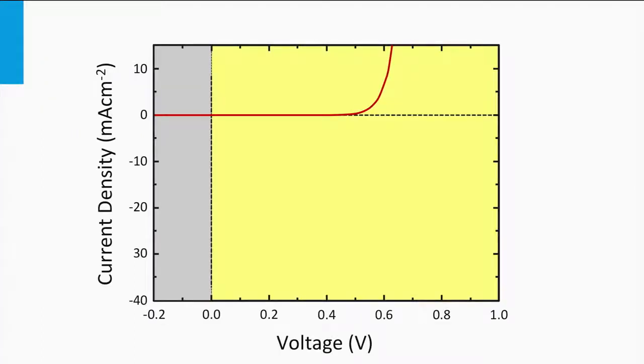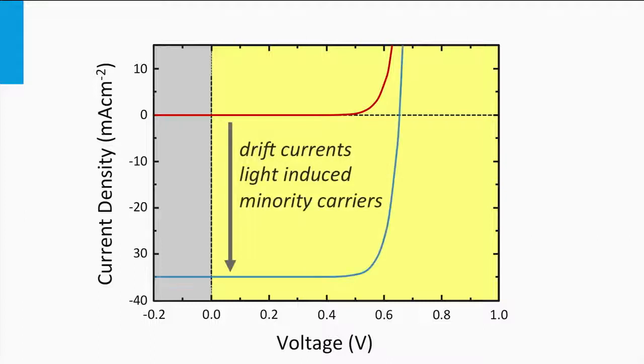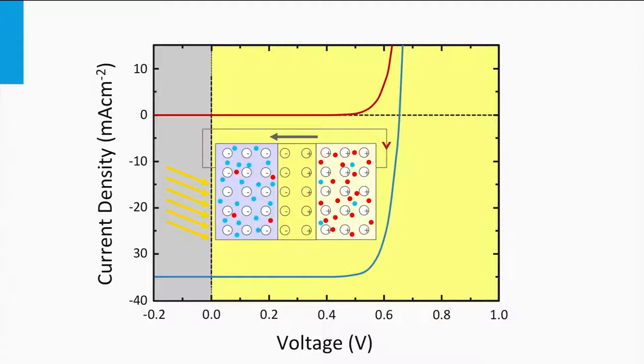Now we look at the IV curve again. The red line corresponds to the IV curve of the diode in the dark. Adding the photocurrent, the typical IV curve of the diode shifts down the vertical axis in the direction of negative currents in reference to the forward bias direction of the diode. This circuit is the circuit for an ideal solar cell. This means that we have not included all types of electrical and optical losses. We will come back to that later this week.